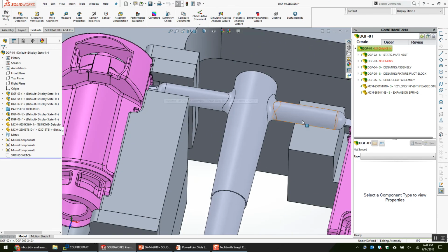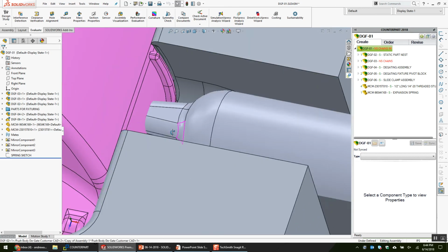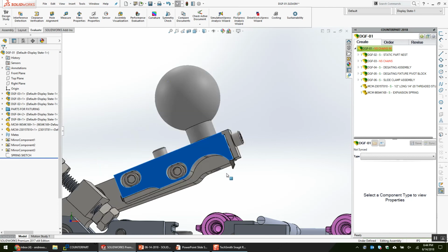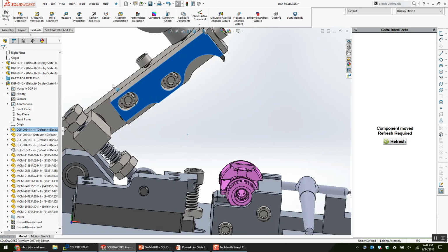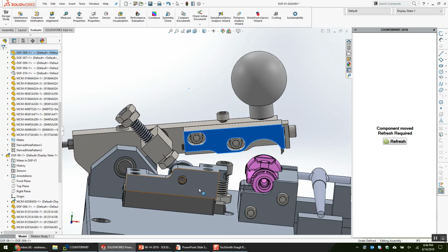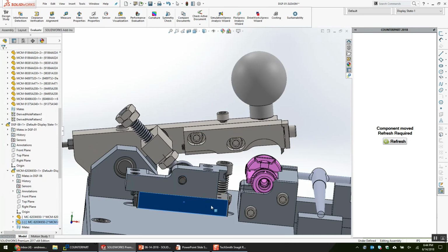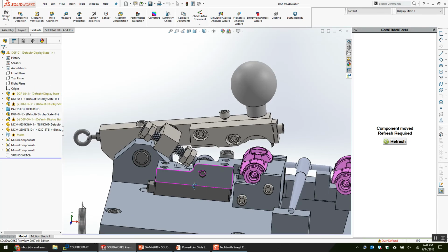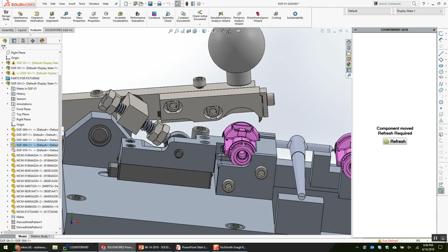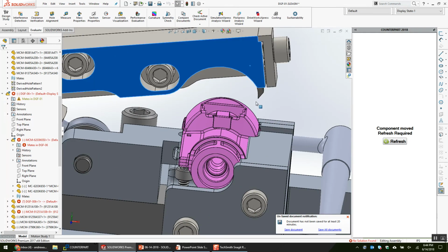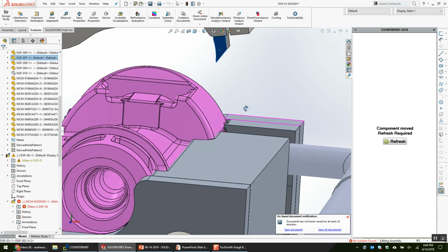But yeah, so this is an injection mold sprue with the two parts. And so here's your gate. And we'll hide this guard. And so when it's up, this pulls this slide back. But then as it comes down, about to there, this is forced forward. For some reason, it's not forcing forward. It's forced forward by the spring and will crowd that part to the side so that this can come down.